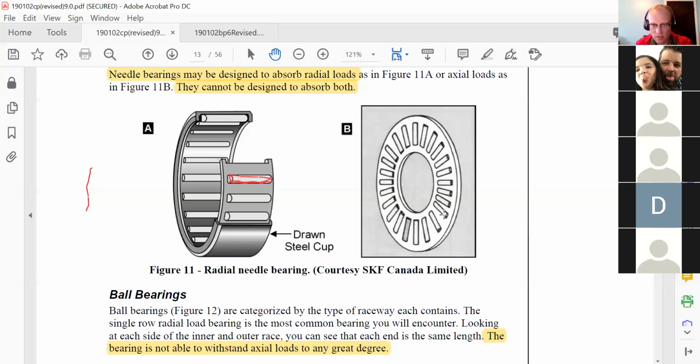You will put it into something, like you said, the tool that you install those trifunctional bushings with. The reason you would have it there is while you are rotating a nut this way, the solid surface here stays still, and you don't want to have wear happening between there. You want to reduce that friction. And so that's why you have a thrust washer on there.